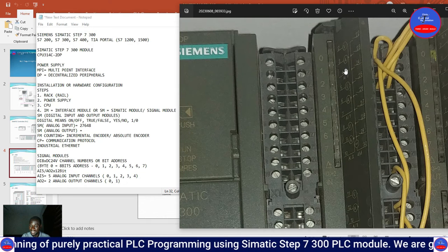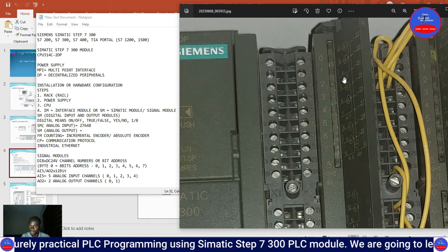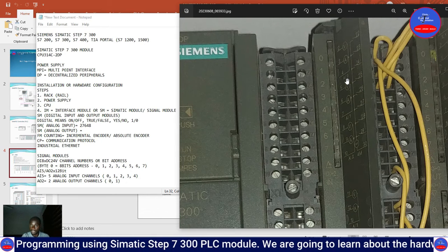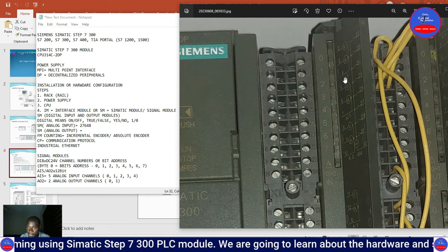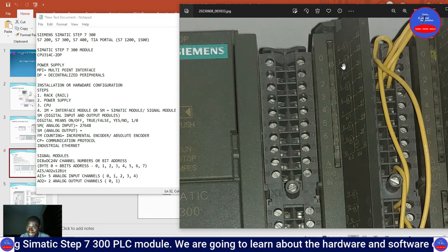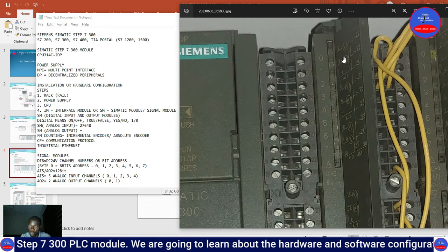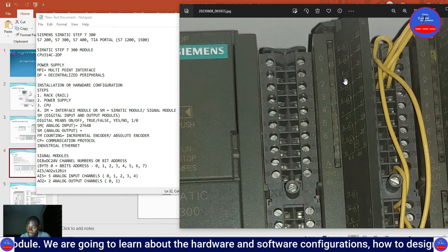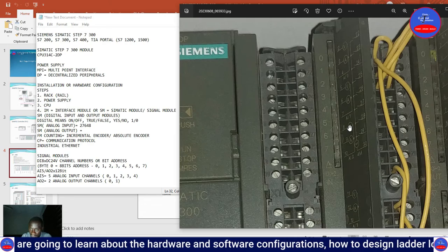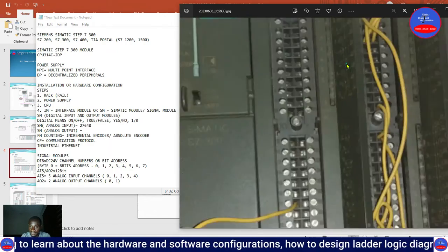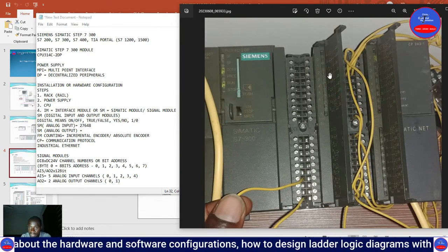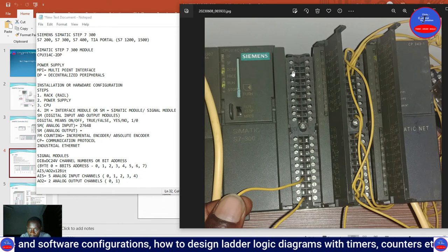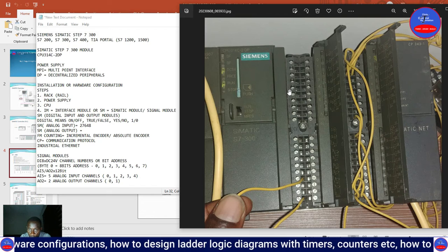And then the 4 is the common, the negative side. 4 will be connected to the negative DC voltage. Now they've written here AI0, which means the whole of this is channel 0, and then channel 1, which also starts from AI1. So this side, the whole of this side, represents this side.